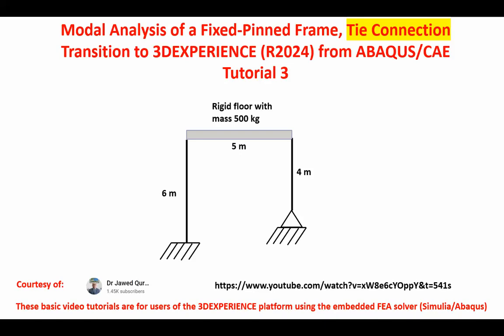There, what I did is draw this frame structure as a two-dimensional sketch in CATIA, and once I exited that, I joined that sketch.